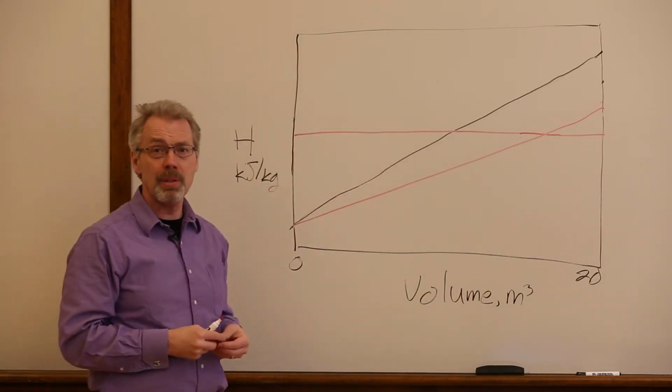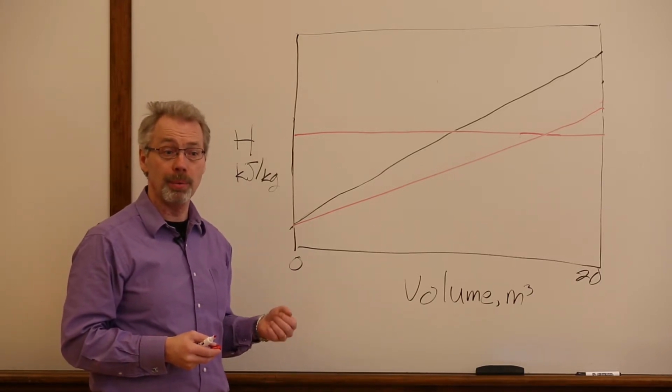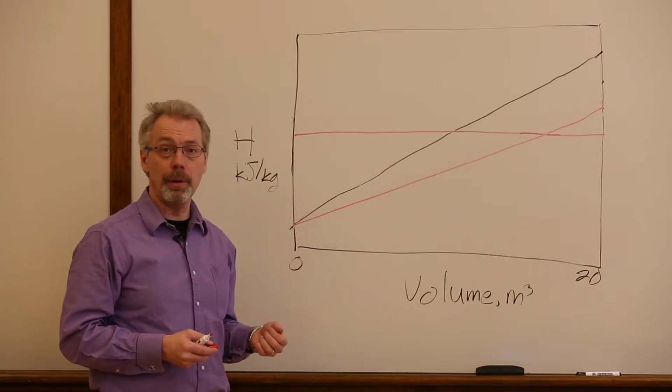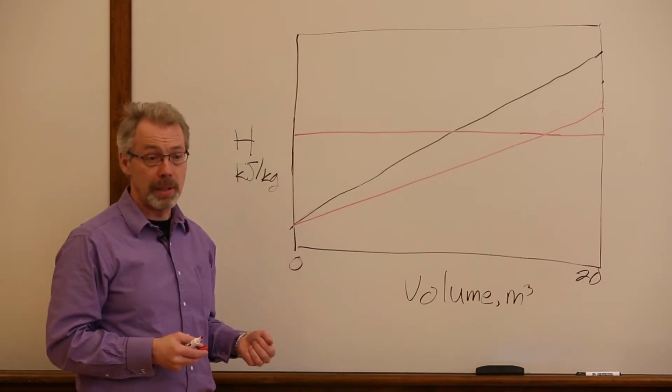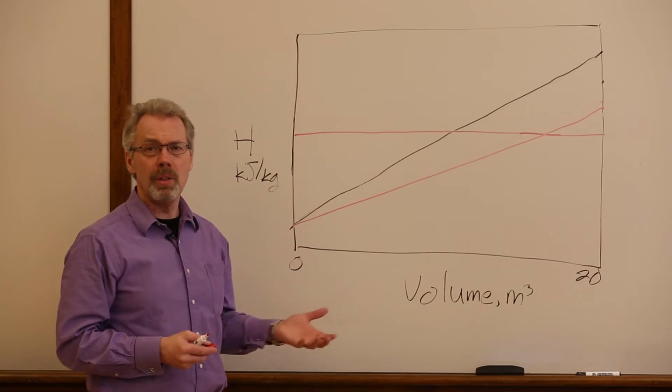We cannot decrease the firing rate anymore, but we can increase the boiler feed water flow rate. This will increase the steady state flow rate of water and steam, but it will decrease the liquid volume that is displaced when the radiant section reaches the boiling point. Let's see how this plays out.